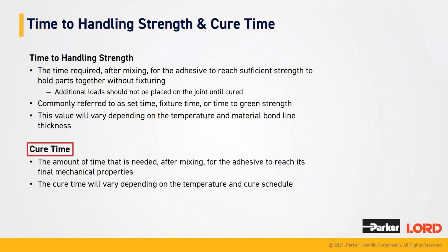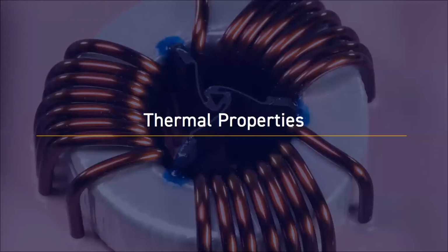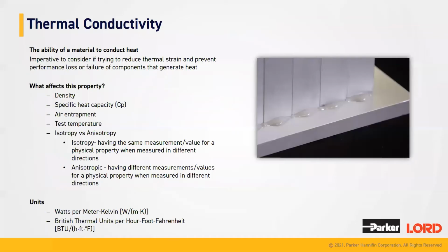The cure time is the amount of time that is needed after mixing for the adhesive to reach its final mechanical properties. So once you hit your final cure time, for example, if the final cure time is 24 hours, that's when you can apply a load. And that cure time will vary depending upon temperature as well as the cure schedule that is selected, so that relates to the temperature. Next, we'll transition on to the thermal properties.